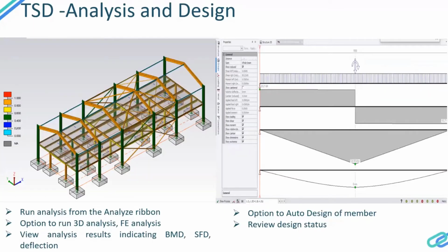So that's auto design. Once we design the member, the next step is to look into the design status, like which members are failing, which members are showing warnings. How to do that? We have the review member option in the review tab. Under the review tab, you will see your design like this. You can see it giving a color code. The green is showing 0.6. Then the red, if there is red in here, it means the member is failing because the ratio is above 1.